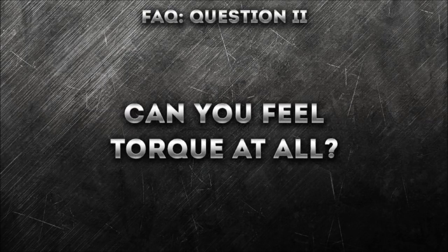Question number 2. Can you feel torque at all? There's one situation I can think of where you can feel torque. With a big, powerful, longitudinally mounted engine, when you have the car in neutral and rev up the engine quickly, the car will slightly tilt to one side. That is the torque of the engine you experience right there. You can see it more clearly by watching the engine tilt in the engine bay when you rev it up.